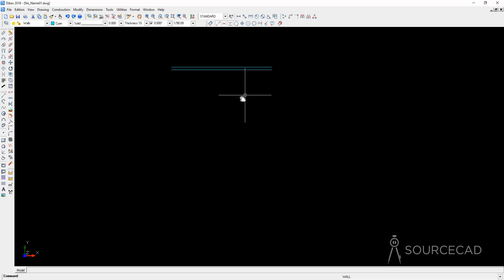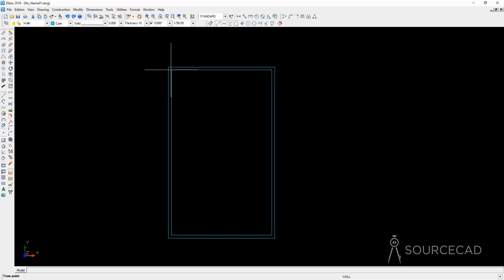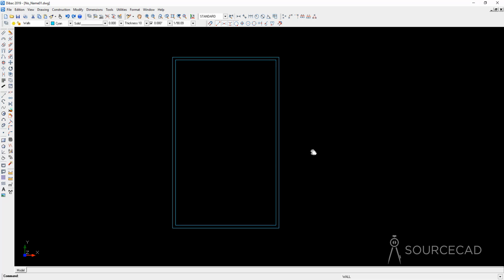All right. Let's go to wall again. And now I'll click here. And once again, we'll start making another wall. So we can just start it right here. And now I'll type 48 again, feet, and enter. And we don't need to exit the command now. So now I'll just go to this side and 30 feet. And I'll join it here. And now I'll press escape key. So here we have 30 by 48 rectangle, which we'll use in this case.